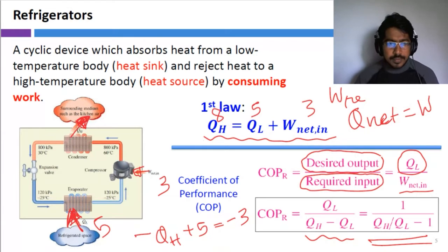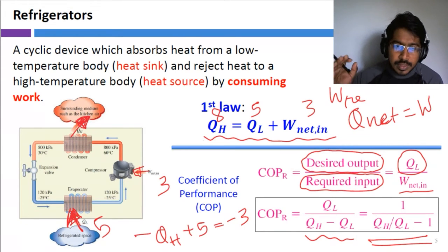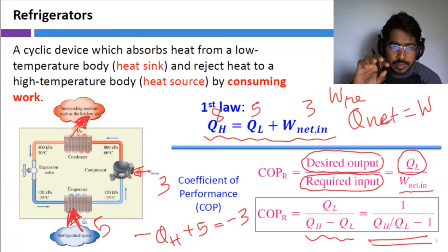The thing is, always think from the inflows and outflows point of view when you're substituting. Don't get carried away by the formulations, because these are just to help you understand, right? If you are not sure which equation to use, always go to first principles and use the basic form of the thermodynamic first law, then derive it yourself using assumptions and substitute your values. Then nothing will be wrong, right?